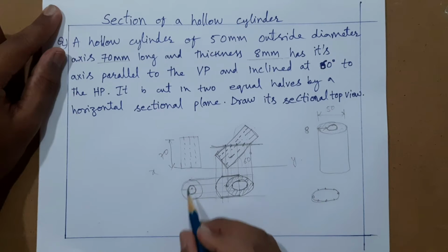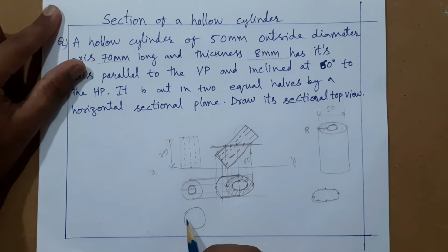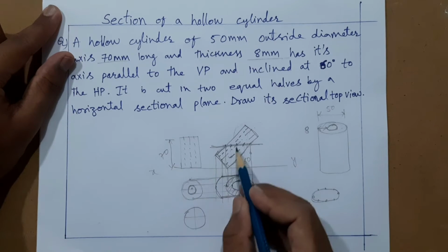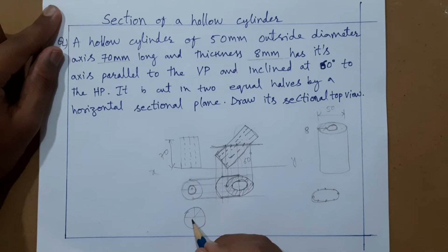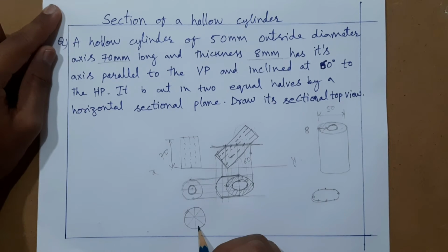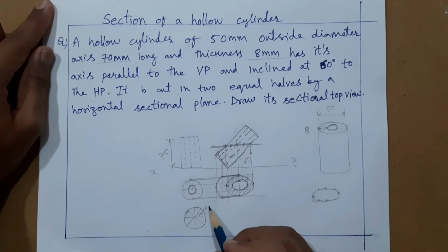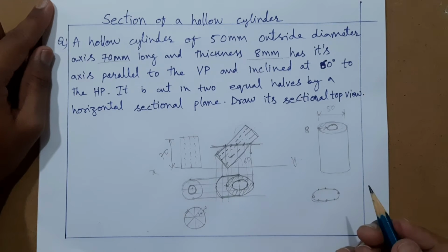So this cylinder, if you see carefully here, I will draw one more time. These are the 4 basic points that already we have got. 1, 2, this left and right, from here we will get 4 more extra points, that is here. So total 8 parts we have divided this cylinder. Some people will go with 12 equal parts also. Here we have divided the circle in 8 equal parts. So each division is 45 degrees. With that more points will come, and your curve will become smoother.